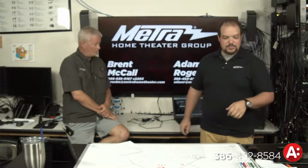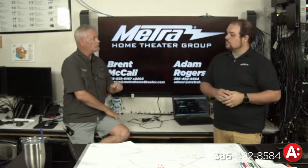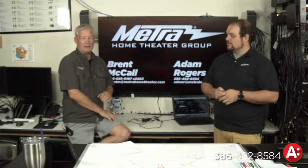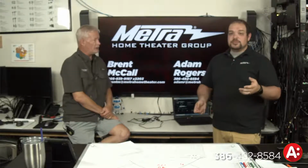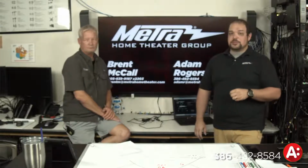And the terminal, in my opinion, is actually an easier terminal to get correct than a standard category terminal, because when you put the wires in those positions, you're done. It really is awesome, and it's not an inexpensive terminal, but it's a great terminal. I would use that terminal even on a standard 10 gig system. You still need to use Cat6A. I would highly encourage you to try those on your HDBaseT and your PoE networks. It will work better and make a huge difference for those types of connections.